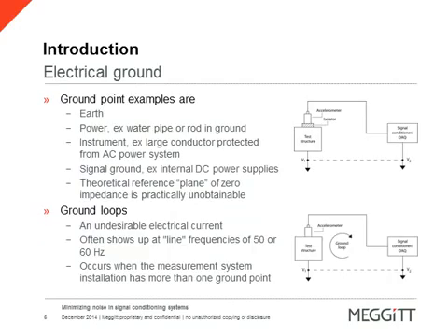Electrical grounds. Earth is the most common and main ground that there is. Next is power ground. Power ground for many buildings, homes, etc. is typically a water pipe or a dedicated grounding rod which is making a solid earth contact and ground connection. Then we have instrumentation ground. Typically that's the third wire common in an AC plug. Inside the instruments there are signal grounds. These grounds can be internal DC power supplies with different potentials, each of those having a different ground reference.